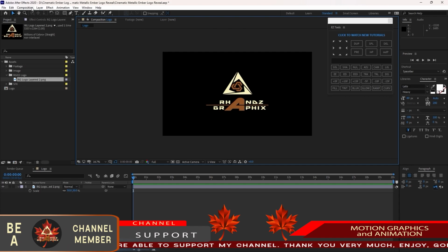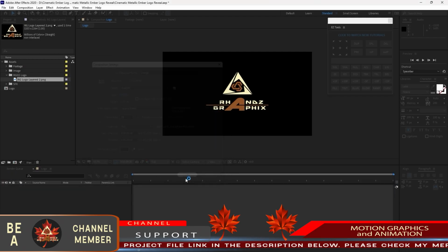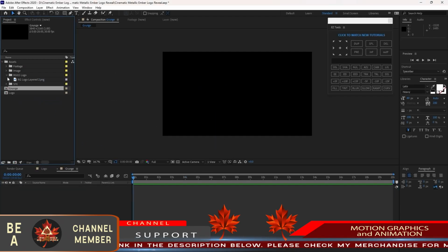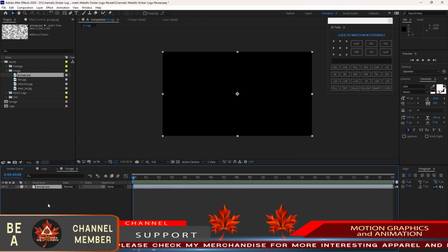Then go to composition, create a new composition. I will name it grunge. 3840 by 2160, 30 frames per second and 20 seconds duration, color is black, click OK. Then open the image, drop down this grunge texture into the timeline.